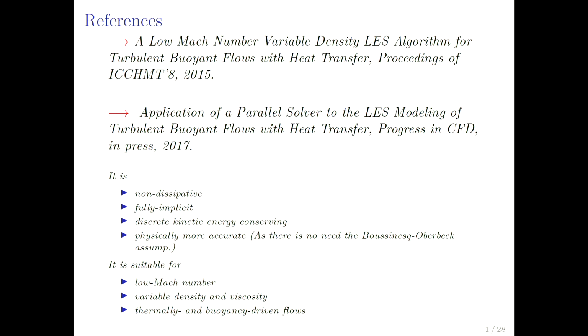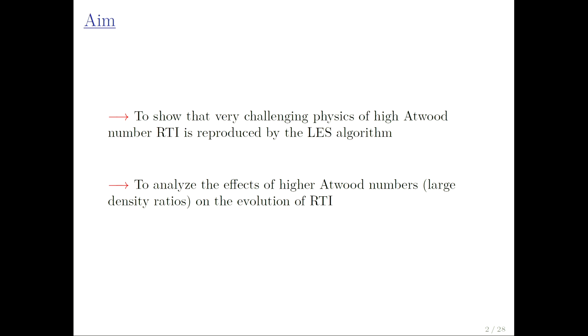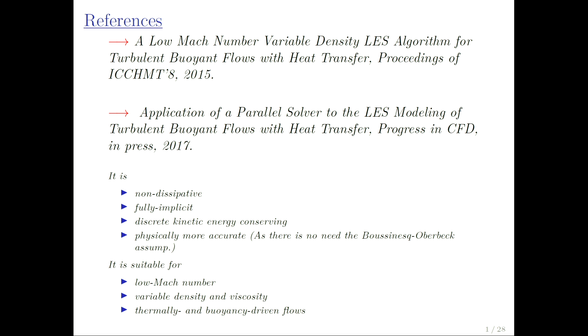Recently, I proposed an LES algorithm, which has some nice features as listed here. It's non-dissipative, fully implicit, discrete kinetic energy conserving at the discrete level, and it doesn't rely on the Boussinesq assumption.